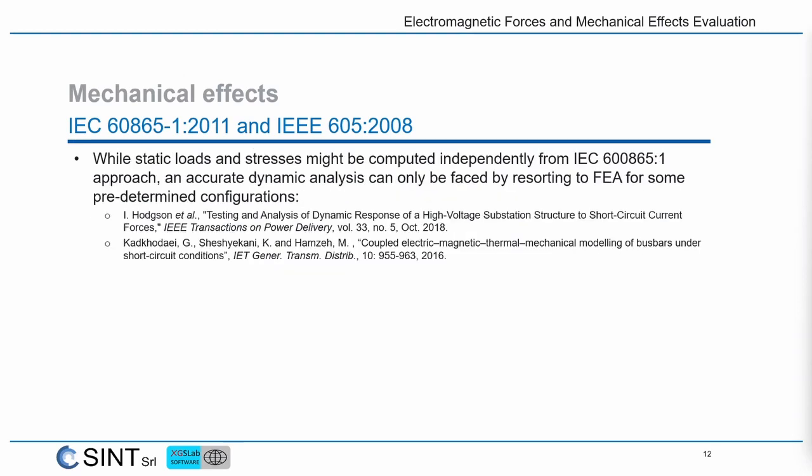For this reason, following the approach of the standard is very important if one wants to keep things quite simple and general. On the other hand, if one wants to accurately compute dynamic effects, it is necessary to resort to some finite element analysis, which has to be carried out for some predetermined configurations on a specific design and layout.